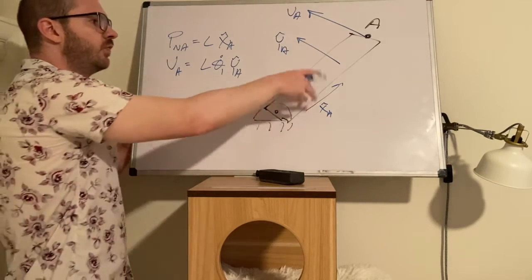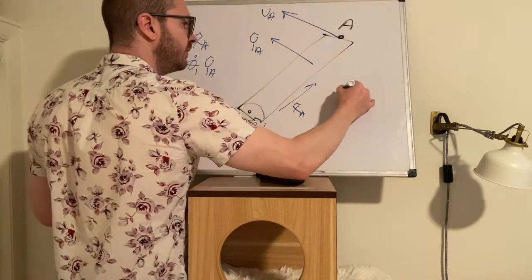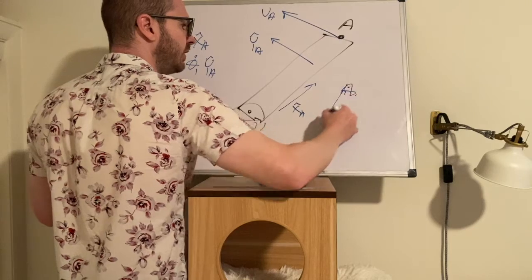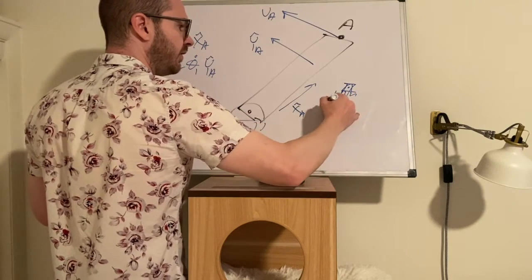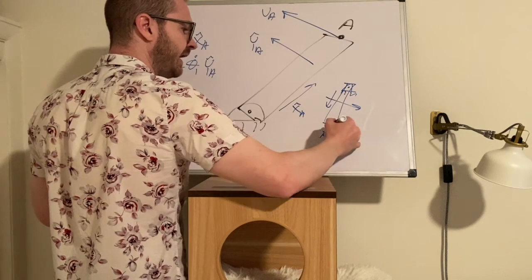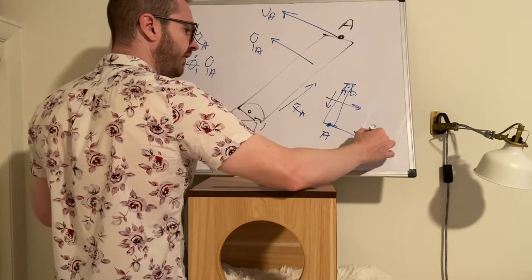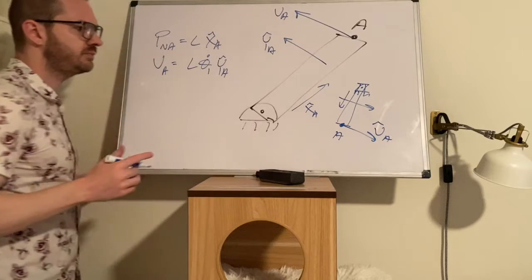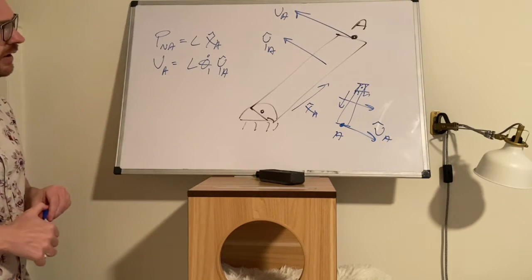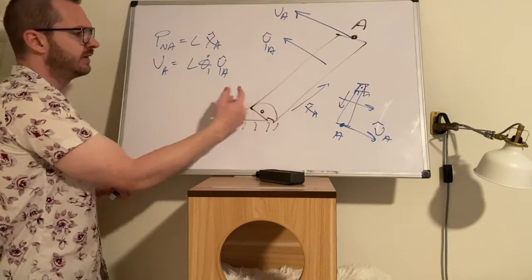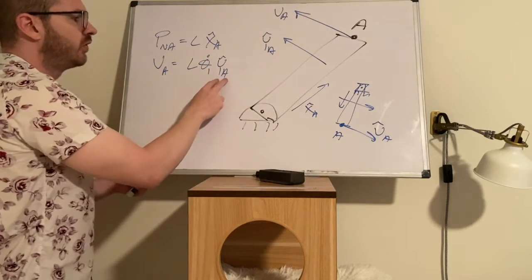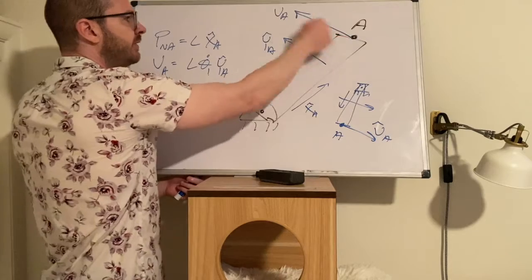And later on, when this pendulum has spun, and point A is down here, there's XA, and that means VA is pointing off like that. So depending on the orientation of the A frame, depending on where the body is, the velocity is going to be rotating with that frame, and it's always going to be perpendicular to the path.